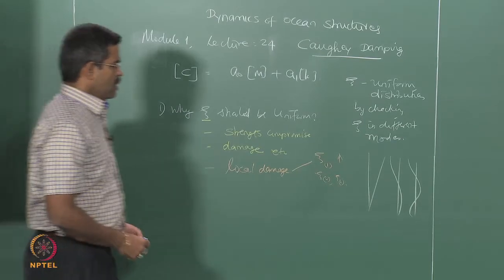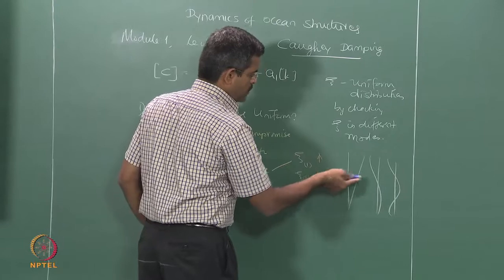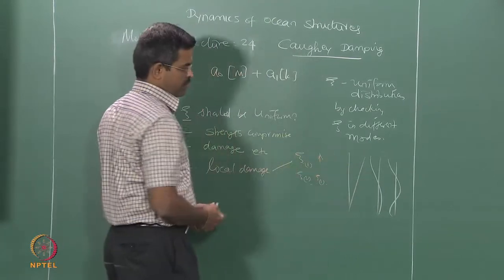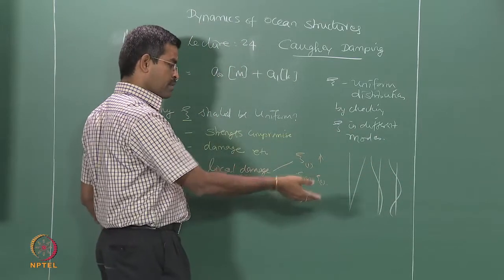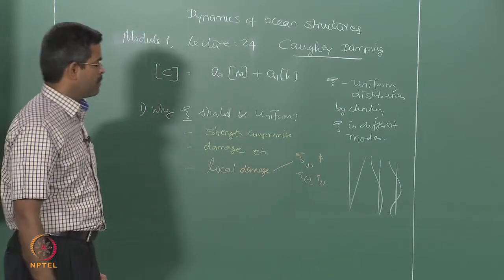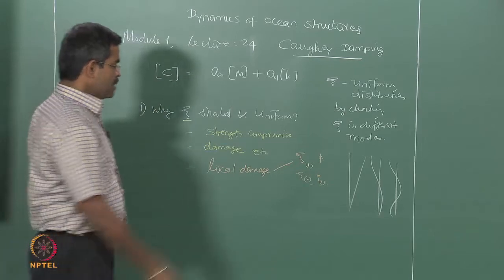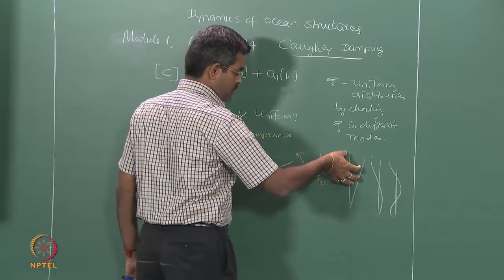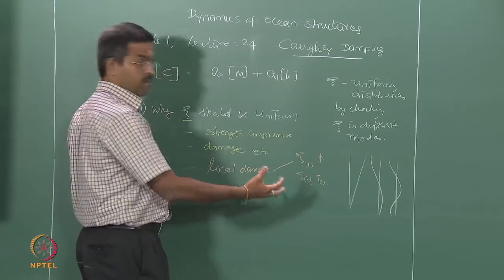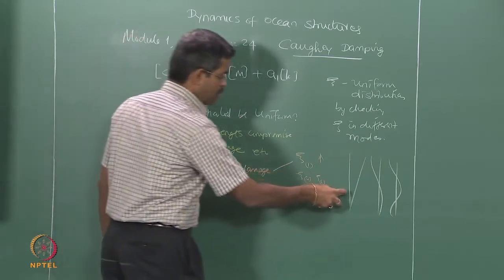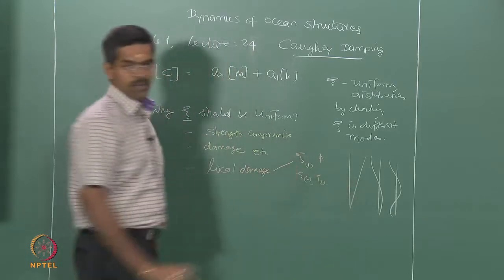So, in the first mode, all mass positions are displaced from the equilibrium position either to the positive or to the negative, either to the right or to the left. So, if the damage is maximum in this first mode, the mass which is displaced by the maximum amount will invoke the maximum damage, the mass displaced by a lesser amount will invoke the minimum damage.